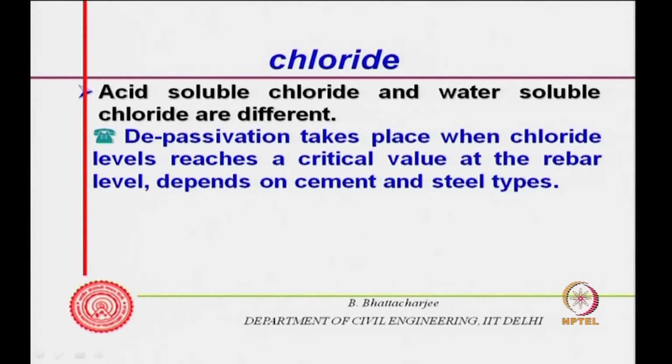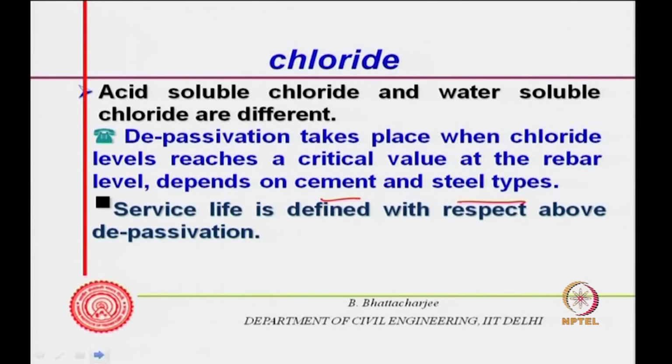Depassivation takes place when the chloride level reaches a critical value at the rebar. This is sometimes called the threshold chloride level, and it depends upon cement and steel types. Service life is defined with respect to the above depassivation.